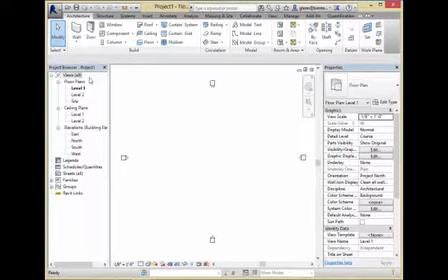What's confusing about your modeling is you want to have the right finished floor, but you don't necessarily want to go through and break up all the floors based on floor types every time a floor finish changes. Okay? So here's what we would really do, and I'll tell you the shortcut for how we typically do it just to make it easier. If I was going to be really, really good about thinking about floors, I would have a type which is the subfloor. A type which doesn't have any finishes on it whatsoever. And I'd lay that out across the entire structure between all the interior walls.